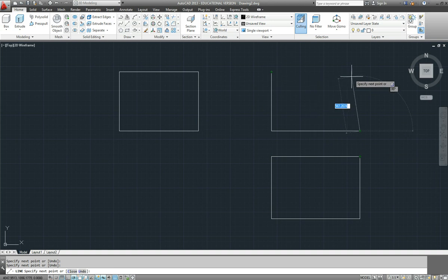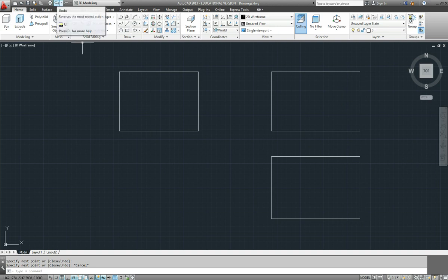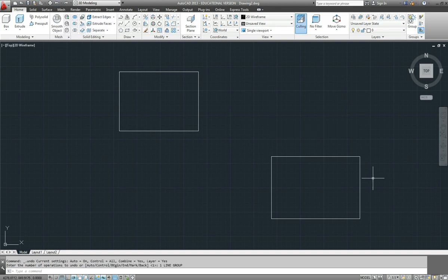So we'll acquire those 2 points and back to the start. So that's one technique for drawing projected objects. Now, I'll just undo that because there's another technique that's more traditionally used in AutoCAD using filters.